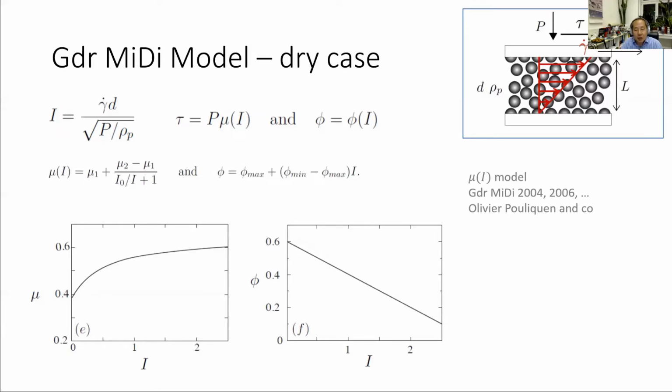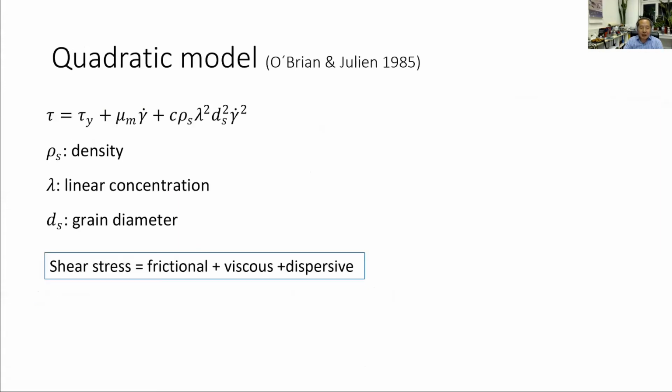This is something we usually don't consider in soil mechanics, right? The second thing here is phi, which is not a friction angle but the so-called solid fraction, right? It's related to our void ratio, more or less the inverse of the void ratio. It is the percentage of the solid divided by the total volume, right?